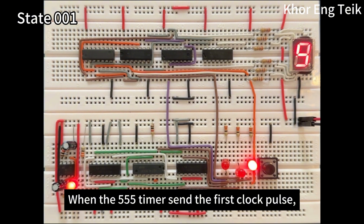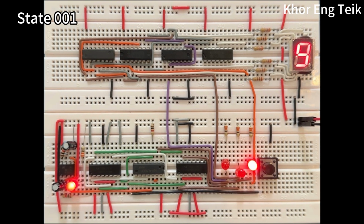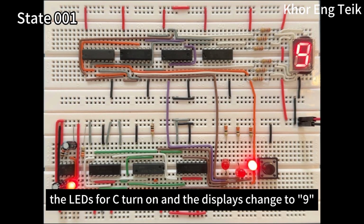When the 555 timer sends the first clock pulse, the first flip-flop toggles. The binary state becomes 0, 0, 1. The LED for C turns on and the display changes to 9.